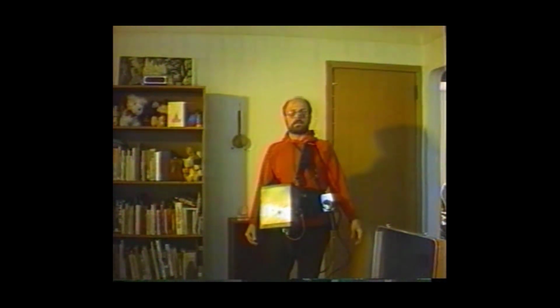Then we go around the house a second time after the blower door has been running for 5 minutes or so. And now any places there are air leakage paths, these areas will get cold, because assuming that we're doing the scan when it's colder outside than it is inside, the areas where there are air leakage paths will get cold from the cold air that's being drawn into the house with the blower door running into the problem areas.